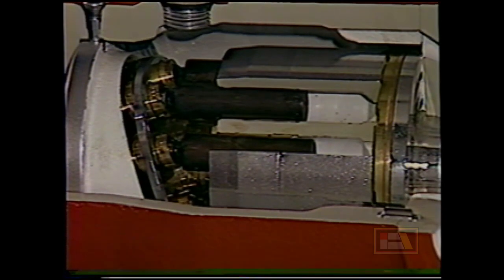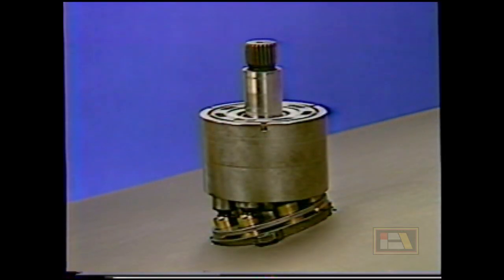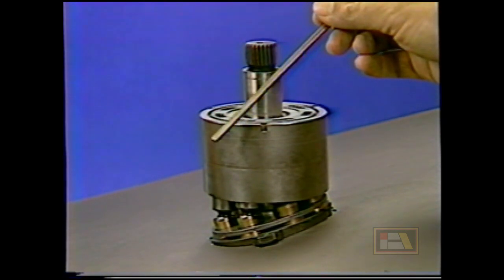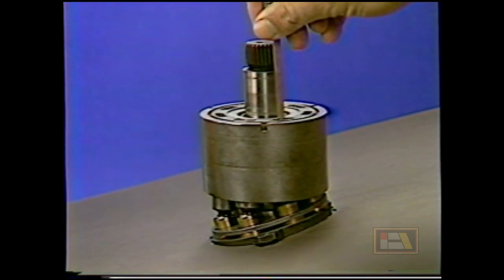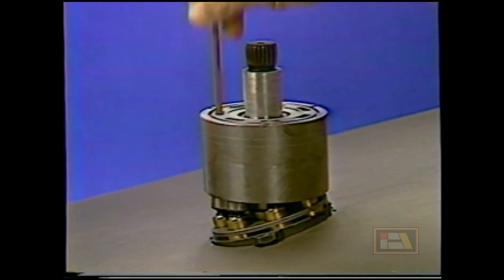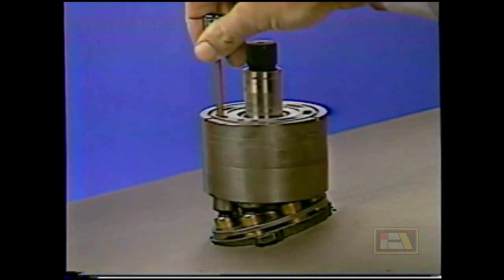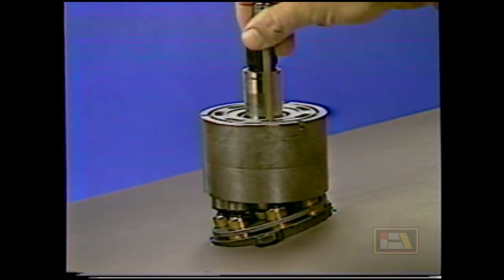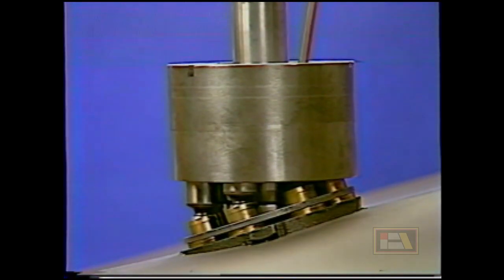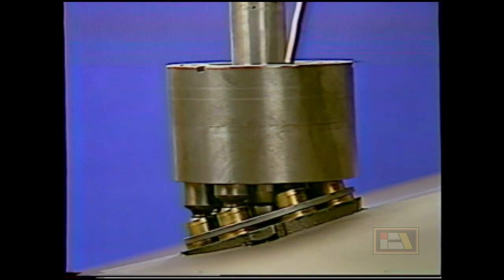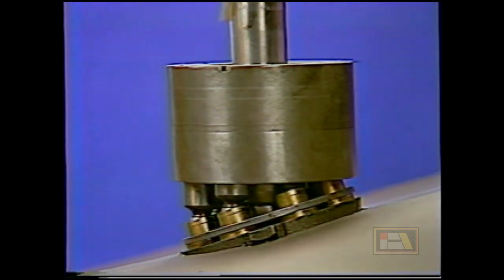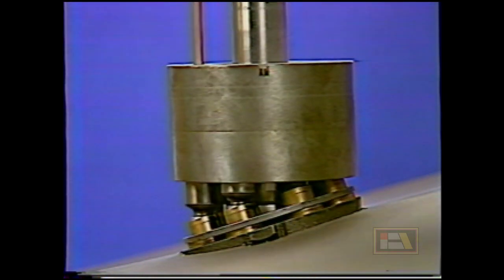Let's look at what causes the motor to rotate. To demonstrate this, we have mounted the swash plate on an inclined plane and the rotating group on a vertical axis. The rod represents oil being forced into the motor from the pump. Watch what happens as this force is applied to the pistons. The ends of the pistons get pushed out of the cylinder block. This causes the slippers to push against the swash plate. Thus, the slippers slide down the swash plate, which rotates the motor. The more oil supplied, the faster the motor turns.